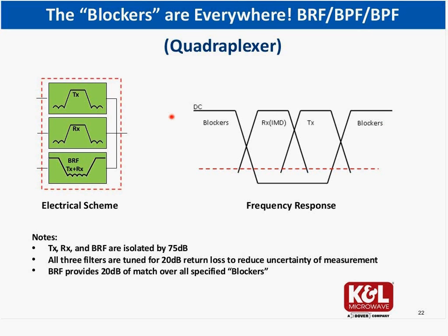Why do I call it a quadruplexer when it's only a 3 port triplexer? You will see in the next slide. I will just hint and say that since the blockers are everywhere, up to 6 gigahertz and above, some of the band rejects will not hold an upper passband that will match the blockers frequencies all the way to 6 gigahertz. And for that, we will have to look at the following solution.